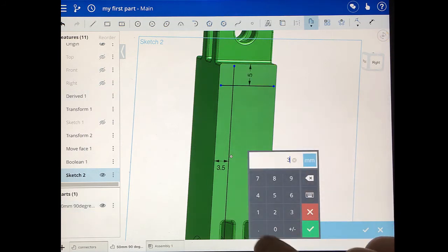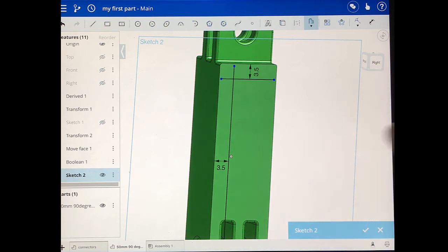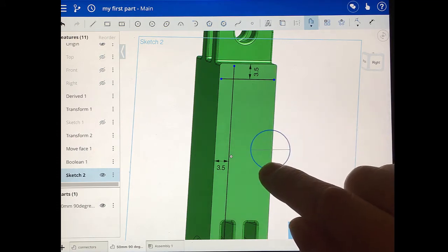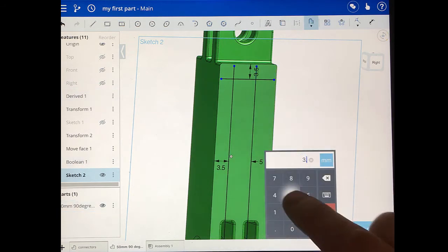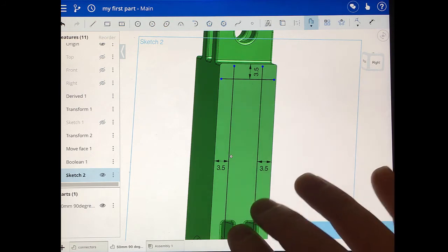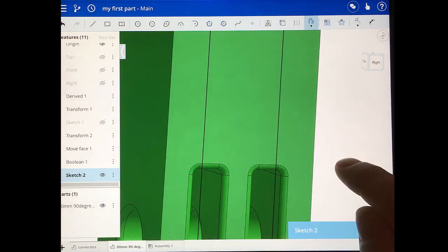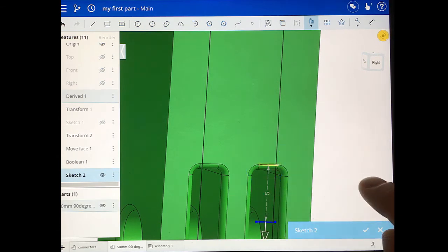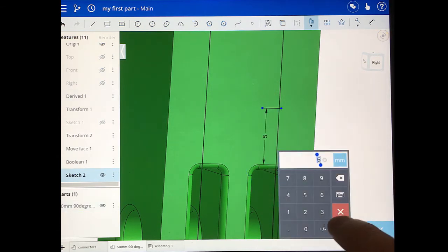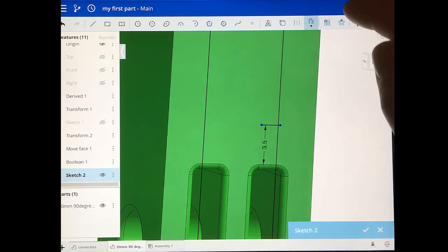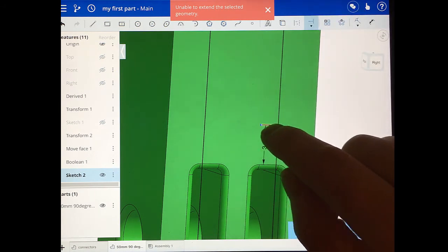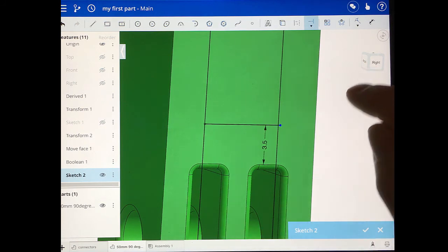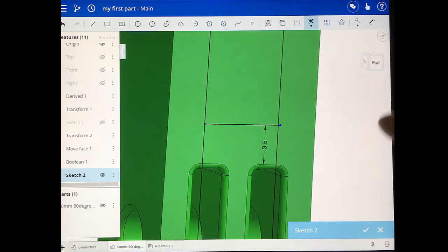There are 3 edges long enough to do this. The 4th edge is a bit short, so we'll use the extend tool to match the line to the perpendicular one. Let's use the trim tool to quickly remove the lines not necessary.